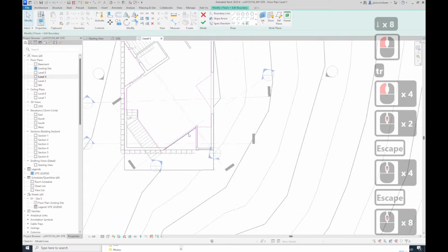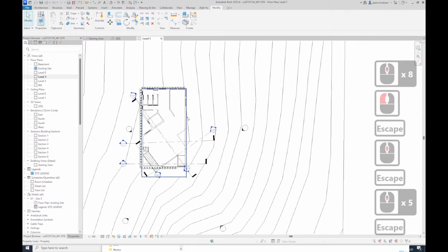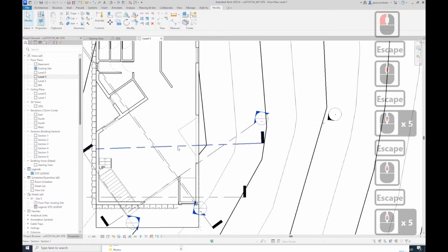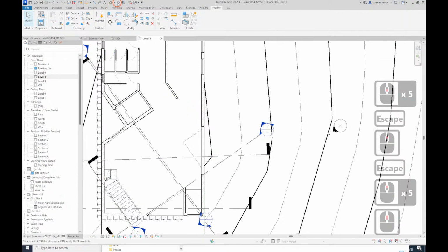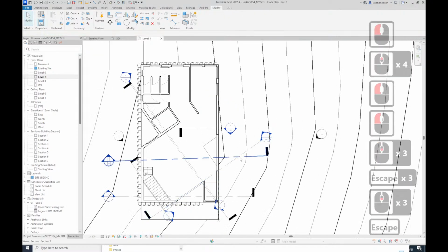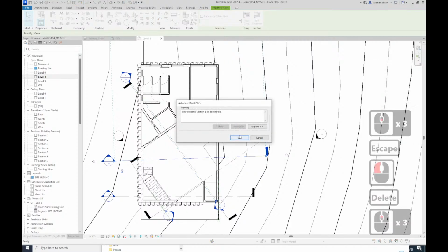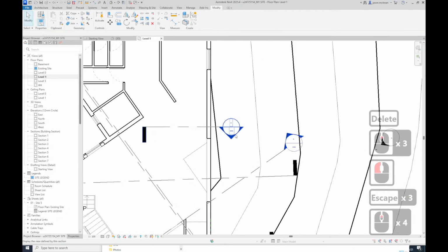Okay, so now you've got that. Good. But typically, just be careful of your walls. This is the only other little thing with Revit. You must try and work square with your wall. If you work at an angle, you'll find that trying to work accurately is impossible. So I'll leave that for now.